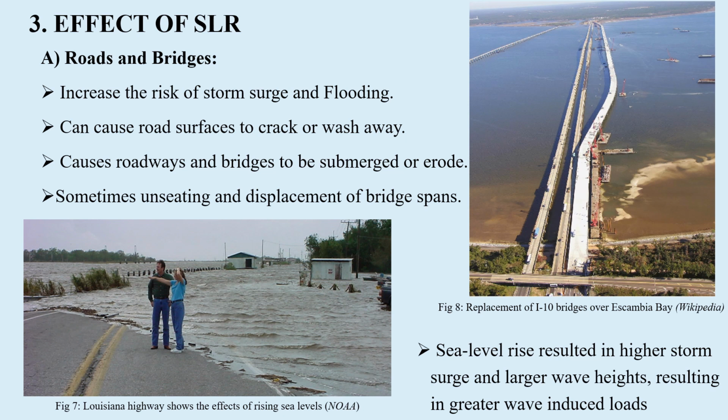Now, let's discuss the effect of sea level rise on transportation infrastructure. It can be said that sea level rise affects various aspects of transportation infrastructure, especially in the coastal areas. Initially, on the roads and bridges, one of the major effects of sea level rise is that it increases the risks of storm surge and flooding, which can cause a road surface to crack or wash away due to the increased water pressure or salt intrusion inside the pavement layers.